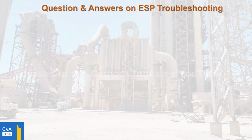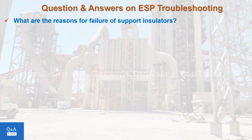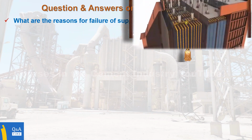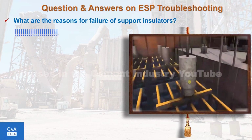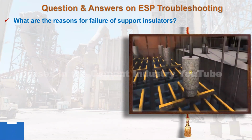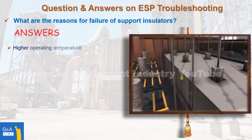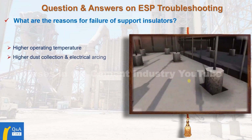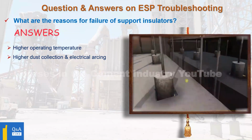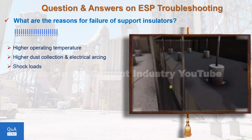Question 8. What are the reasons for failure of support insulators? Answer. 1. Higher operating temperature. 2. Higher dust collection, and electrical arcing. 3. Shock loads.